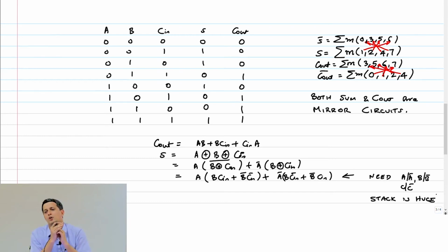So now we come back to our earlier discussion where we said it is okay for the sum to be generated a little later than the carry out. While the sum is being generated, the carry out can propagate, no problem. So you actually have time to generate the sum after the carry out has been generated and propagated. Right? What we are going to do is, we are going to see if we can use this carry out that we created in order to create the sum now, so that we can simplify our expression.